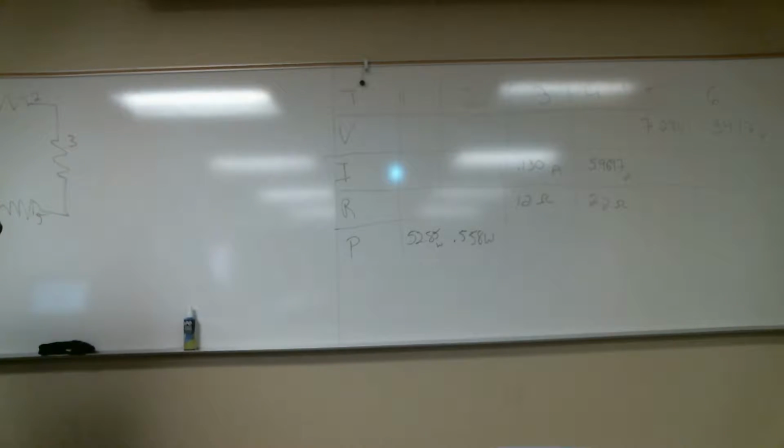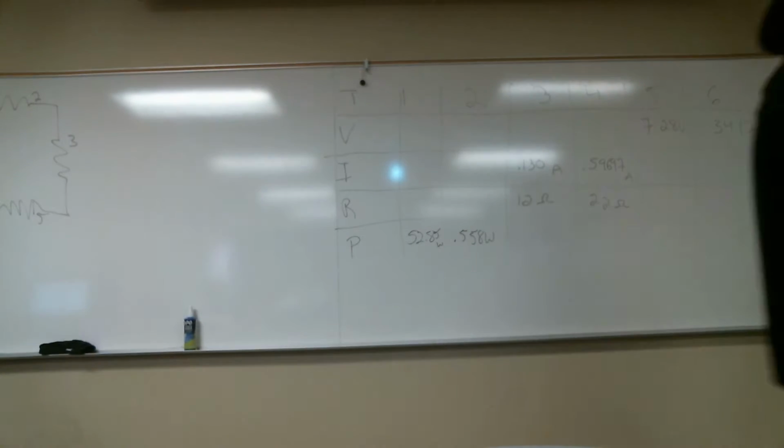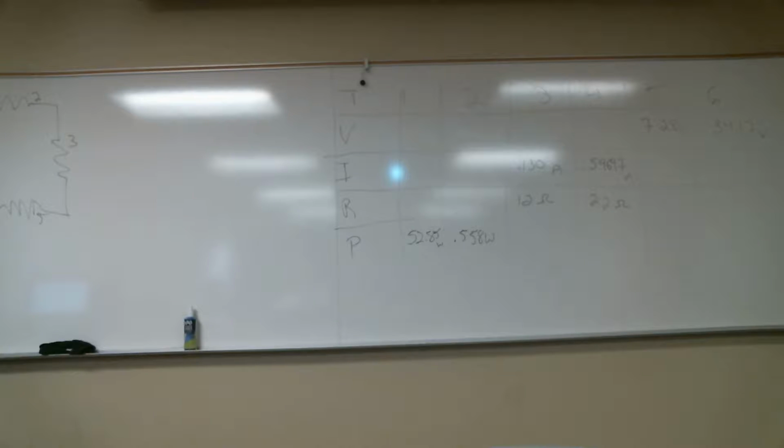So, what's kind of the first general rule? Just do any math you can do, right? Well, maybe even before you do any math, since stuff is kind of scattered around, is it possible for any values that are up there that were given to be plugged into other places? So in other words, if I had two parallel resistors, the voltage drop across one would be the voltage drop across the other, or the current going through one in series is the same as the current.